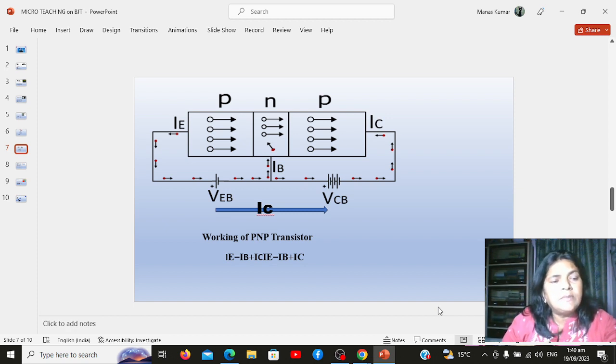So, here are some important facts about BJT. There are two PN junctions, hence a transistor may be regarded as a combination of two back-to-back connected diodes. The collector region is wider than both emitter and base. The base is much thinner than both emitter and collector. During the transistor operation, a lot of heat is generated at the collector, hence the collector is made larger to